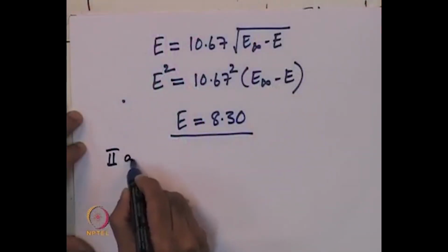So, what we are saying is that even for root m a factor of 3 higher than Q, the reaction is almost totally in the diffusion control regime, that is in the instantaneous reaction regime. So, now since we made the approximation of the denominator, that is the hyperbolic tangent term in the denominator being equal to 1, we can test out that assumption by calculating the second approximation,